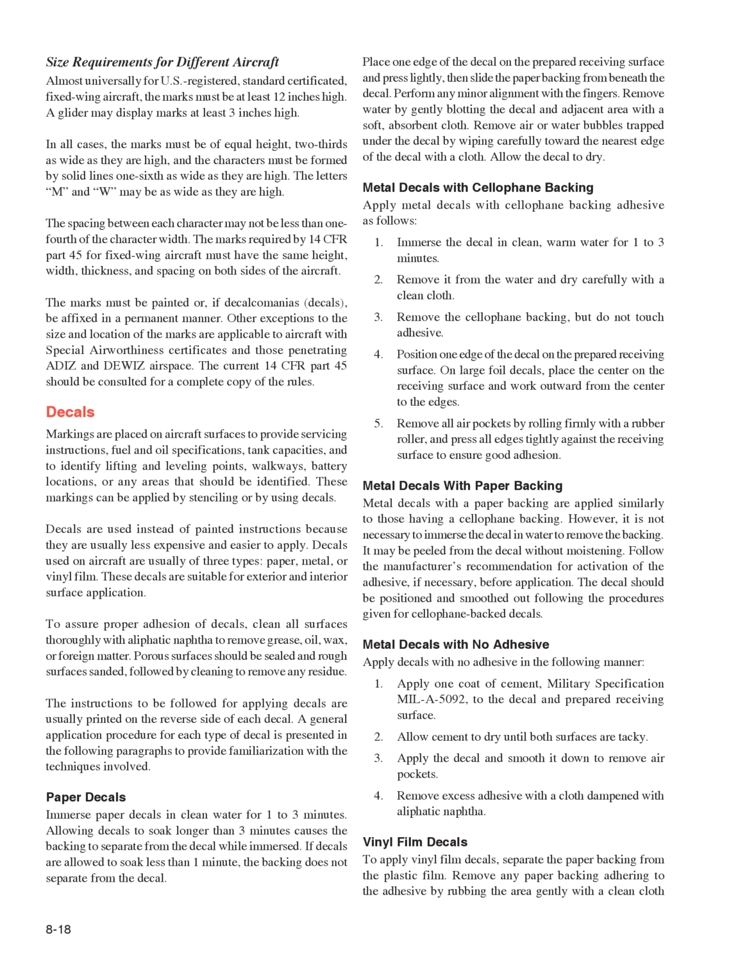Decal markings are placed on aircraft surfaces to provide servicing instructions, fuel and oil specifications, tank capacities, and to identify lifting and leveling points, walkways, battery locations, or any areas that should be identified. These markings can be applied by stenciling or by using decals. Decals are used instead of painted instructions because they are usually less expensive and easier to apply.